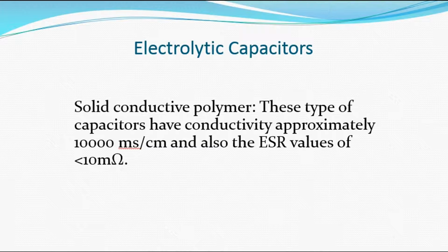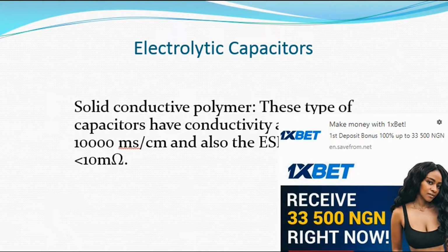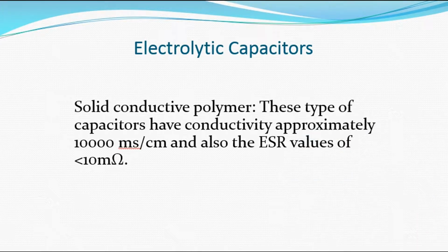So from what I have just said, this solid conductive polymer type of capacitor has conductivity of approximately 10,000 Siemens per centimeter, and also an equivalent series resistance value of 10 milliohms.